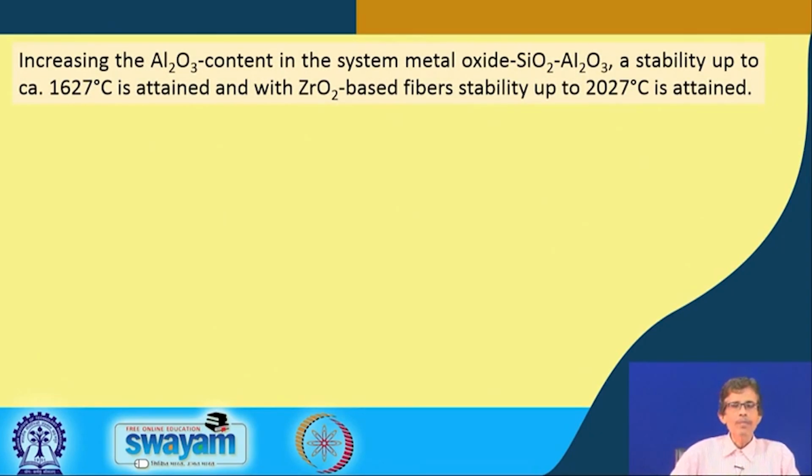So, we can have certain types of this fiber where we can have alumina, we can have silica and other types of metal oxides. So, you see these inorganic fibers we can think of as the typical metallic fiber, but the metallic fibers will not have that capability, that means they cannot have that much insulation capability. So, we can think of another naturally occurring thing that we will also discuss, that is asbestos. Asbestos fibers are also very good and useful inorganic fibers which can be used for your temperature insulation.